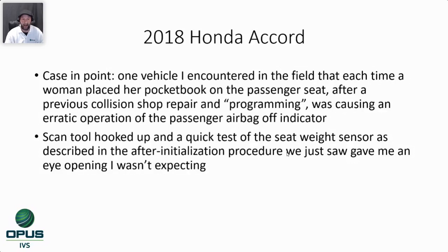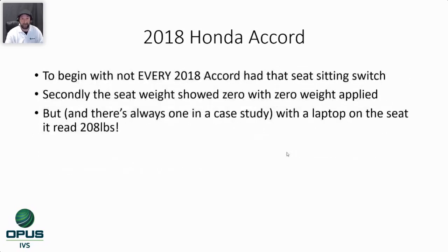What we saw just gave me an eye-opening that I was not expecting. I'll tell you that when I first went in there, it has a seat setting switch, which, by the way, if you looked at the wiring diagram, it did not have it there. However, I had an input and it was there. It was on the scan tool.